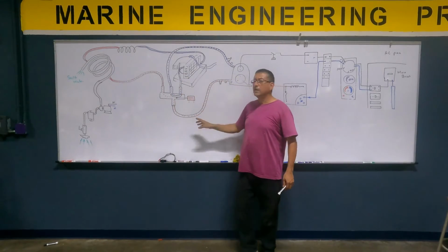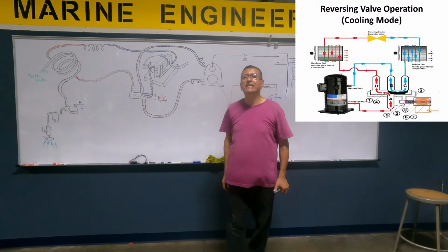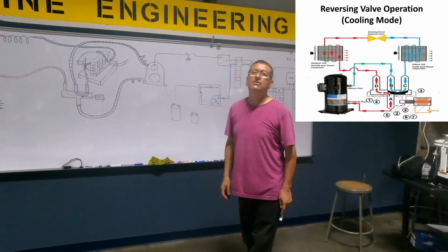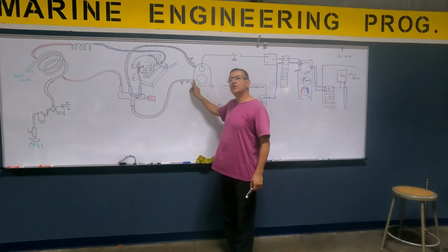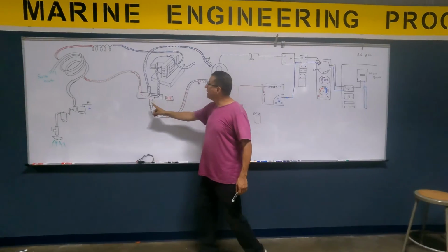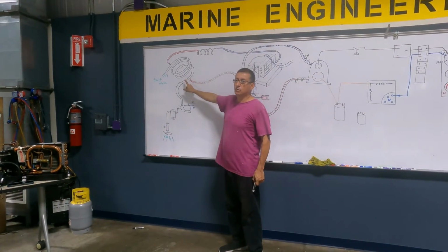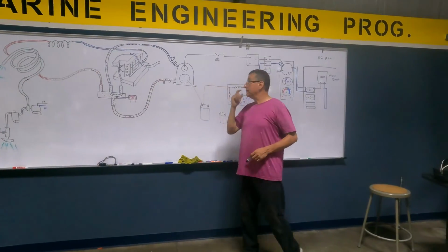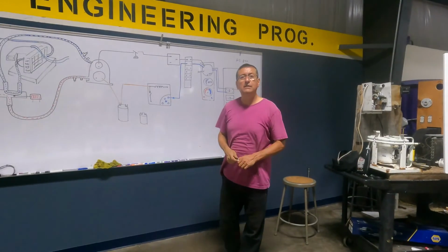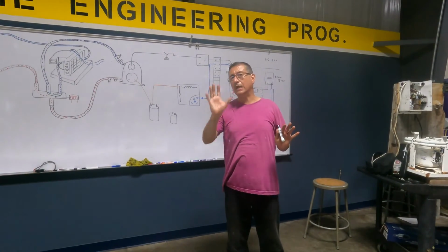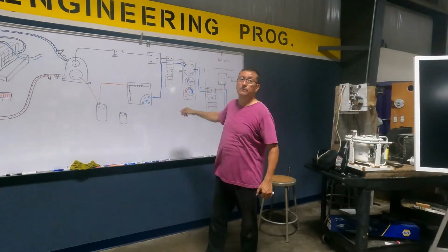In this moment, in what mode is this picture? Is cooling mode or heating? It's in cooling mode. Is cooling mode because the discharge of the compressor is going directly into the outdoor coil. Is cooling mode. Okay. Is clear those three buttons, guys? Yeah. Those three buttons are exactly like you have in your car. A lot of boats, they have those controls.